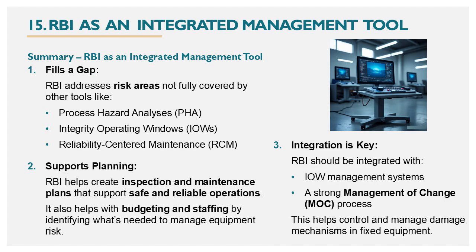Agenda number 15 is RBI as an integrated management tool. Finally, we'll discuss how RBI can be integrated with other systems like reliability engineering, maintenance planning, and safety management for a holistic approach. Summary of RBI as an integrated management tool. Number 1 is fills a gap. RBI addresses risk areas not fully covered by other tools like Process Hazard Analyses, or PHA, Integrity Operating Windows, or IOWs, and Reliability-Centered Maintenance, or RCM.